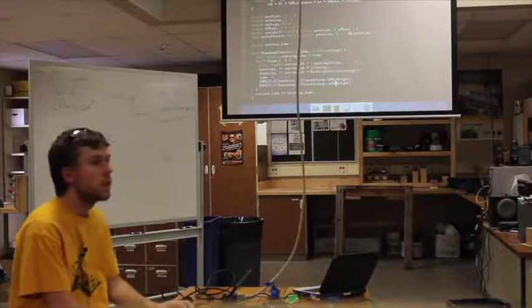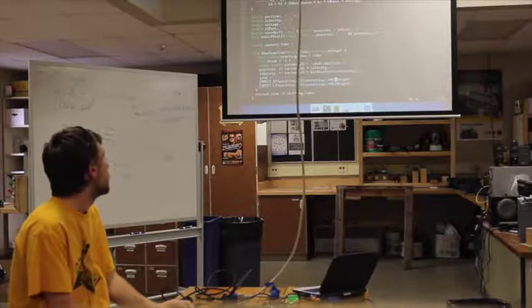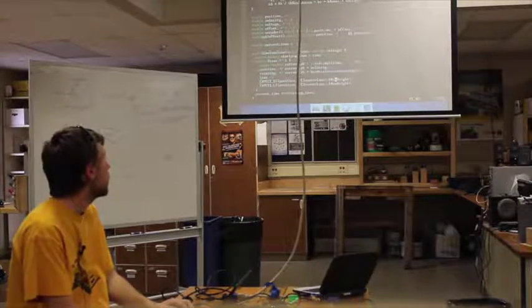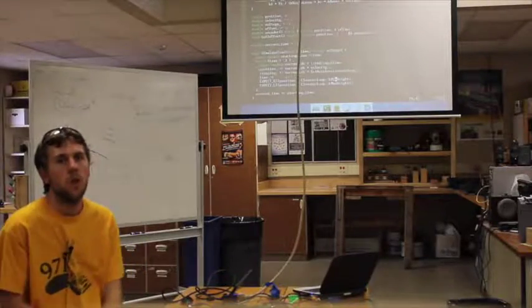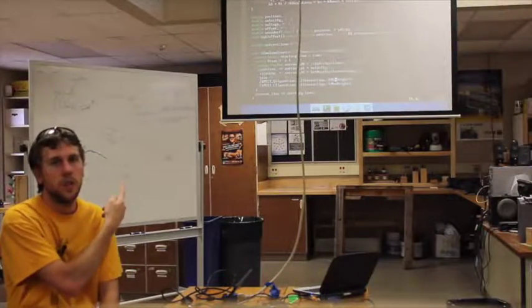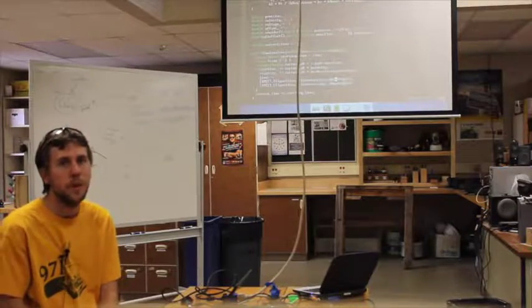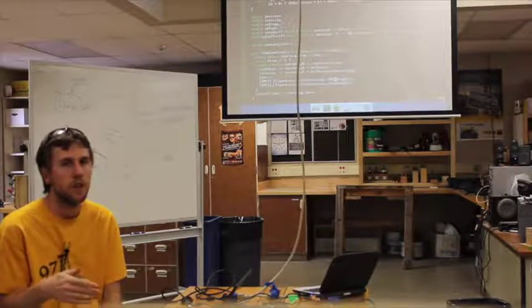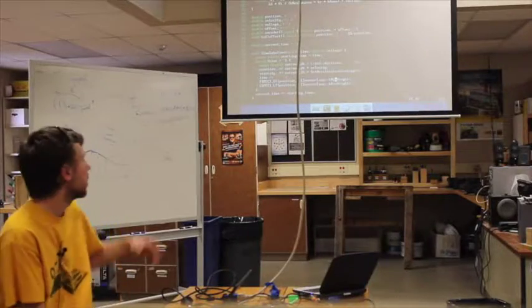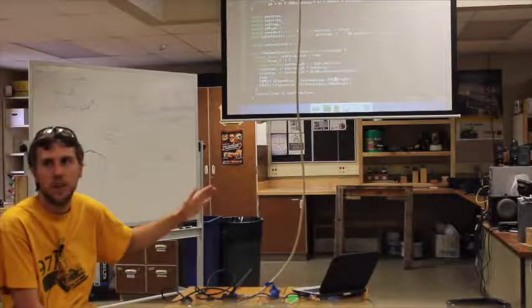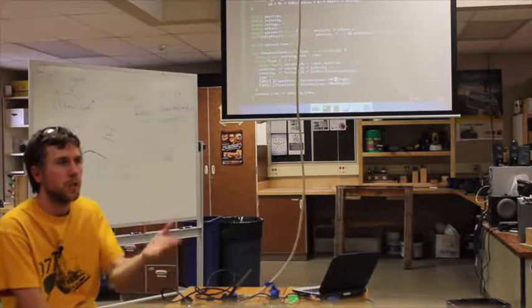Is there any reason you're not using assert in this instance? There are two things you can do when something like this fails. One is you can completely shut the program down, and the other is you can mark the test as failed and try and continue and see what happens. Expect says, if this fails, mark it down as a test failure and then keep simulating. Assert would just kill it.